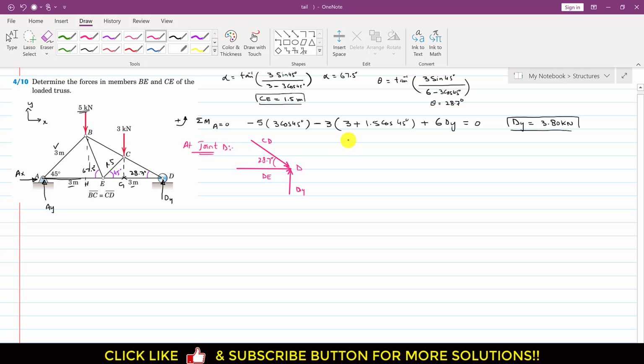So now at joint D, if we apply the summation of forces along y equals to 0 and resolve these forces, this CD force will have one component acting downward. This is the sine component, acting in the negative y. So I will write minus CD sine of 28.7 degrees, and this Dy is acting in the positive y direction, so plus Dy, and this equals 0. We know Dy is 3.80 kilonewton. So from this equation, the force in member CD is 7.91 kilonewton. As this CD force is acting towards the joint, this means it is a compressive force, right?